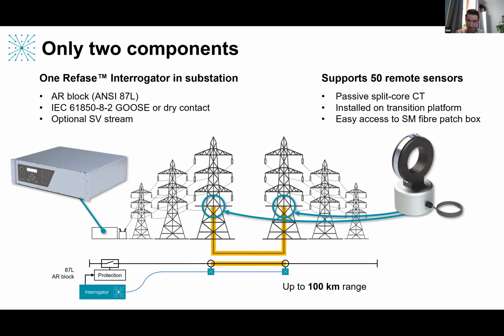And then at those transition points for CFD, we would just splice our sensors, daisy chaining them into that network. So in series, we would have each of our sensors spliced into that fiber. Because it's hardwired in the fiber, you don't have to rely on wireless transmissions, and everything is transmitted directly back to the interrogator. Another point to make is that with all the sensors, there's no active electronics there. They're not necessarily transmitting a signal.